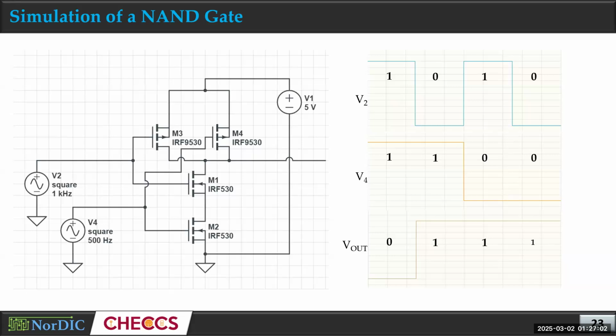Try to keep some separation between the two PMOS. After putting the two PMOS, if you have maintained the minimum separation, you can click on the design rule checker. After every step, you can check the design rule. Then, I think you have an overlap, so there will be an error.